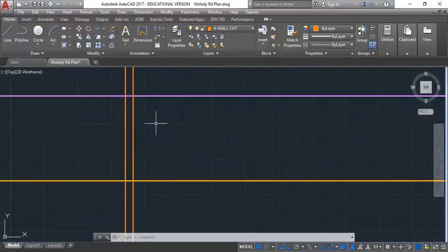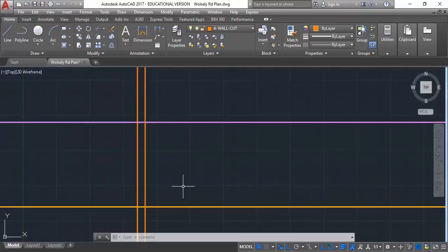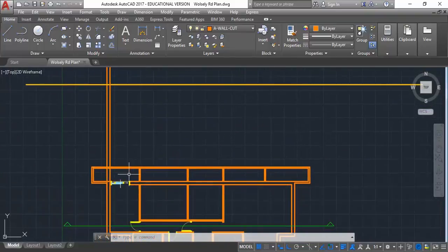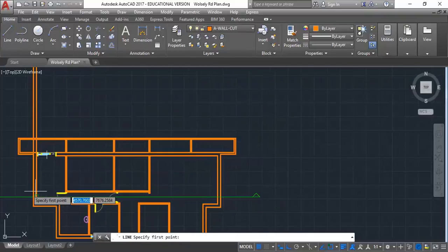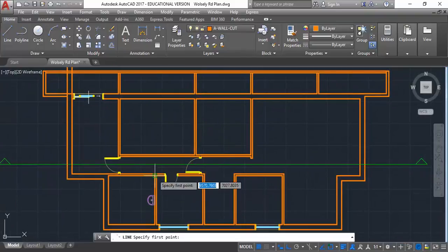So if you're worried about the floor thickness or even the ceiling structure and the thickness above, you don't really need to be, because chances are you're not going to affect anything either below that line or above the ceiling. So I'll offset those later. And so you can keep drawing lines up from the floor plan. And a common approach is just to go through and work out every point that the section line is crossing.